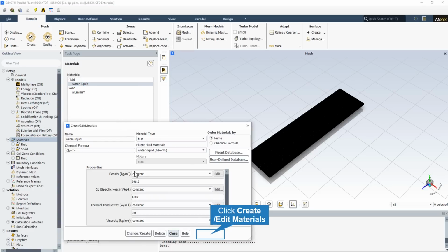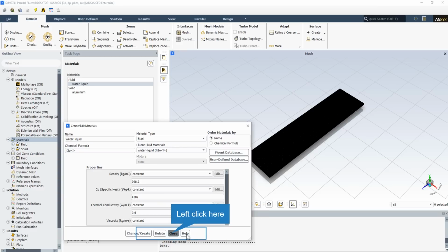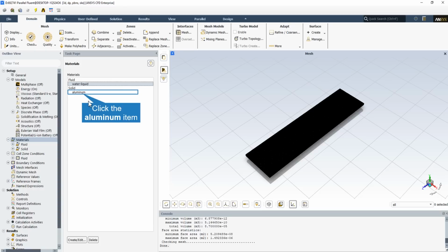The fluid that is going to be used in this CFD simulation and as the main flow for the heat exchanger is liquid water. So we define all the material properties in the material tab. And all the walls of the heat exchanger and also the Chevron plate are assumed to be aluminum as the default solid material of the Fluent software.